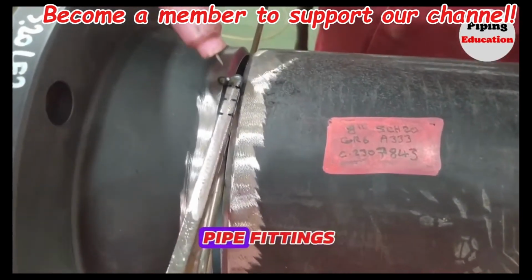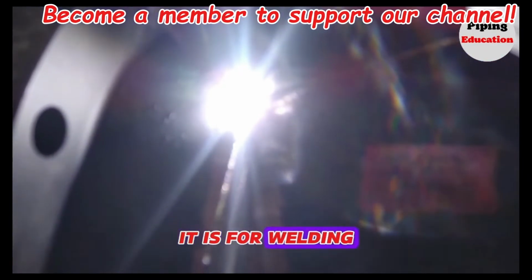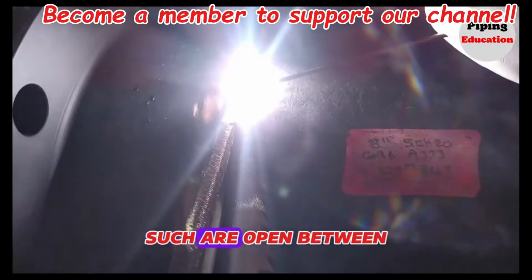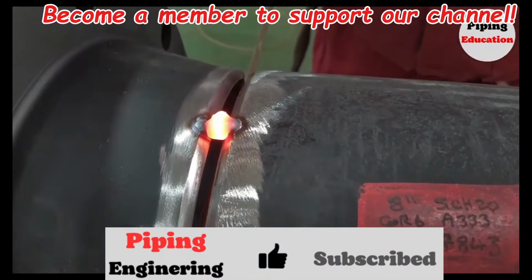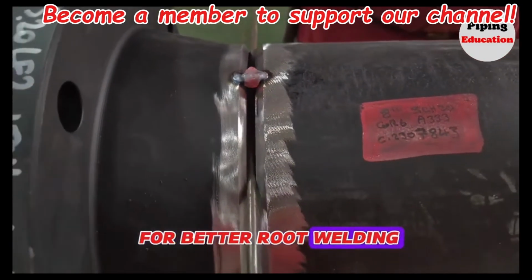During fit up, between pipe fittings there should be a gap of approximately 3 millimeters, it is for welding. You can see this gap for welding now in this video. During fit up, such gaps are opened between the pipe fittings to be welded, a gap of approximately 3 to 4 millimeters. Having this 3-4 millimeter gap is for better root welding.